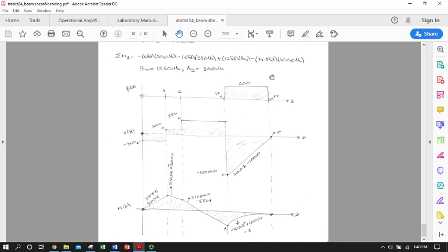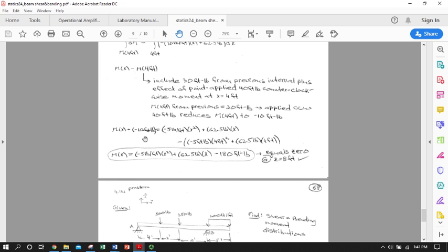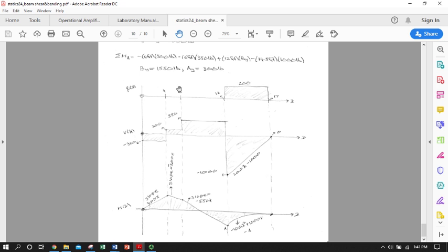So this graphical method of expressing shear, distributed load, and bending moment based on different regions of loading in the beam, handshakes at the limits, at the endpoints of these regions, and then most fundamentally, the sign and the integral derivative relationships between these functions really gives you a lot of insight on a kind of a gut level of what's going on, and it serves as a super valuable check of your algebra calculus method if you do both together.